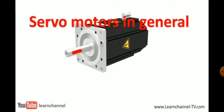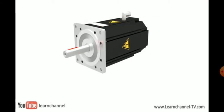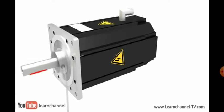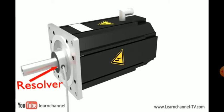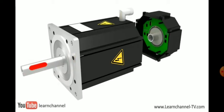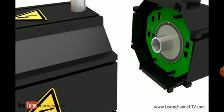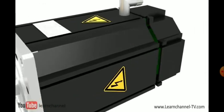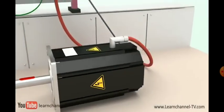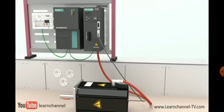The servo motor is a part of a servo drive, whether brushless DC motor, synchronous, or a robust asynchronous motor. But one thing in common is the detection of the rotor position by a sensor. This can be a resolver or an encoder. In this case, you see an incremental encoder. This sensor device gives feedback to a controller to keep, for example, the rotational speed or torque constant, or to reach the target position as fast as possible. The servo motor system includes the servo motor with its feedback device, a servo amplifier, and a controller.